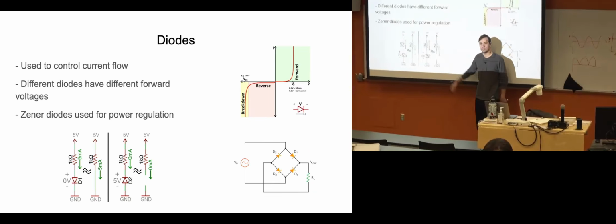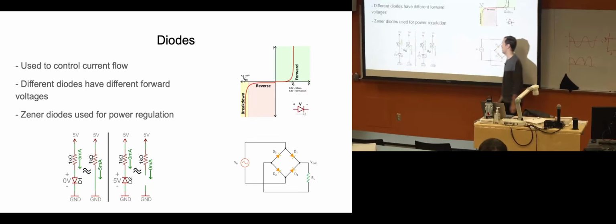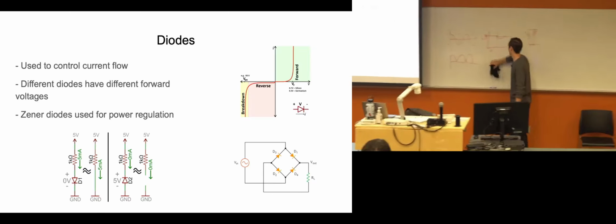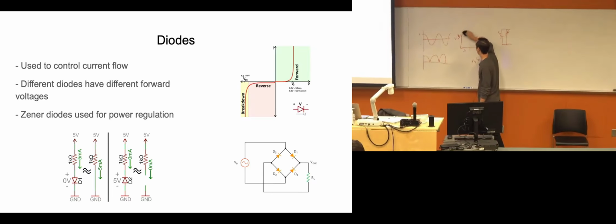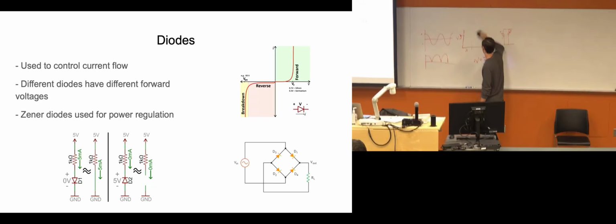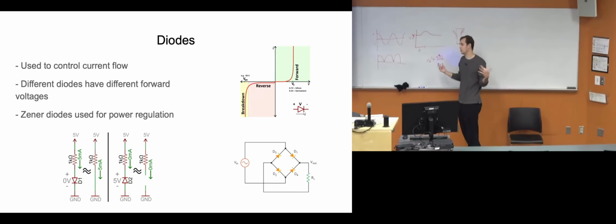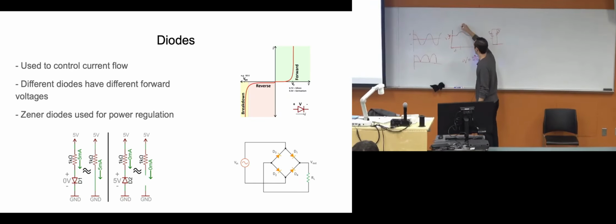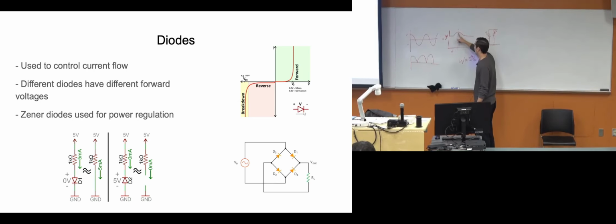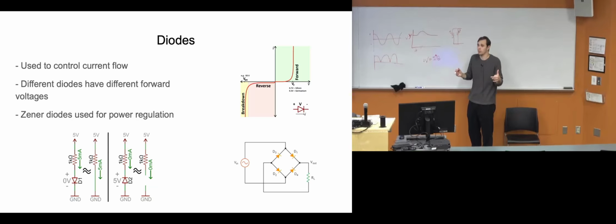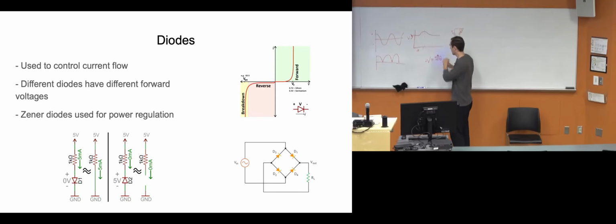We're in an embedded systems class, so we're going to talk about Zener diodes for power regulation. Similar to this scenario over here where we have a voltage droop, where it went down and we were risking a brownout. Zener diodes are especially useful when we have something like a voltage peak. Like let's say you had a power surge on your voltage supply for some reason. Right here, this could overvolt your system and maybe fry your CPU. Or fry components, could permanently ruin the board, right? That would be pretty bad.